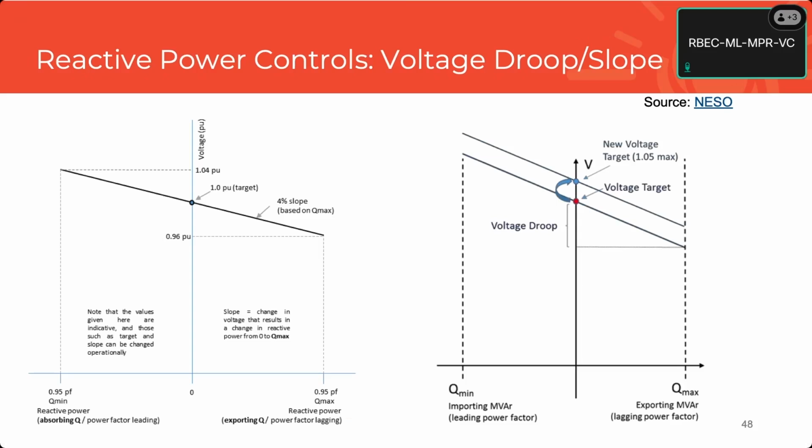If you put it at 0 and you have another reactive power controller right next to it, we really have now 2 devices that are measuring voltage, maybe not at exactly the same place, maybe they're slightly separated, and one of them has a voltage of 1 and the other has a voltage of 1.01.